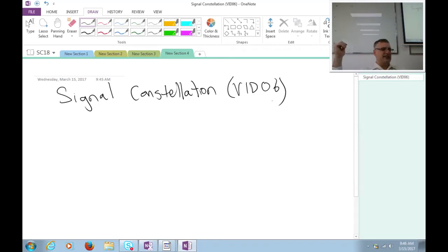And we can get fluctuations like that in satellite TV. If we're operating up at 11 or 12 gigahertz to broadcast a video signal down to Earth on the downlink, well, now there'll be some slight path loss changes as I move from the latitude and longitude of my geostationary Earth orbit satellite to a few hundred miles to the right or to the left. That might make a dB or two difference. And that can actually change the performance of a satellite link.